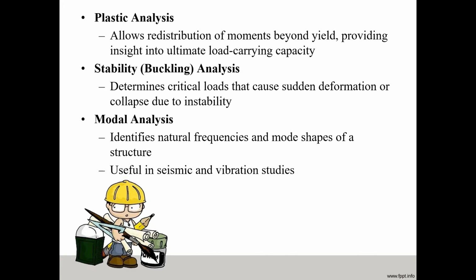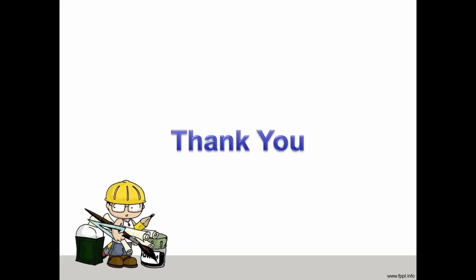Then the next is stability analysis, otherwise called buckling analysis. It determines the critical load that causes sudden deformation or collapse due to instability. The next is modal analysis, identifying the natural frequencies and mode shapes of the structure, which is useful in seismic and vibration studies.